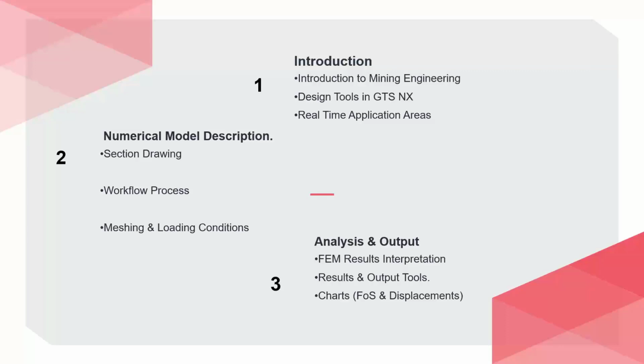I will tell you that while I take you to the numerical model. In the third, it is the basic analysis and output of FEM results, the output tools, and the factor of safety, since it is an open pit. So we will have the factor of safety, and then the displacements and strains and the stress distribution.